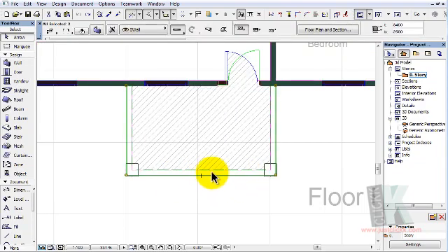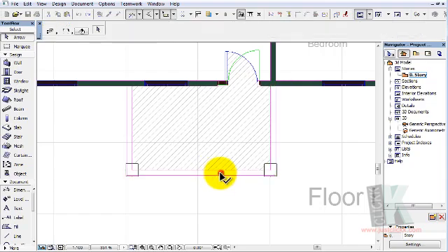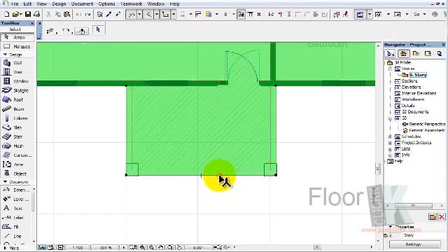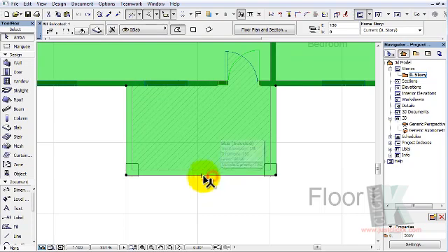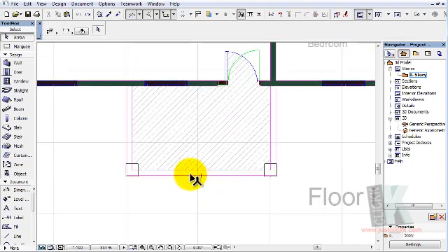The wall you're accessing here is not actually the ArchiCAD wall. This is the AutoCAD wall that is behind the slab. So to access the ArchiCAD suspended wall that you just created here, you will have to look at the story that is handling that wall.